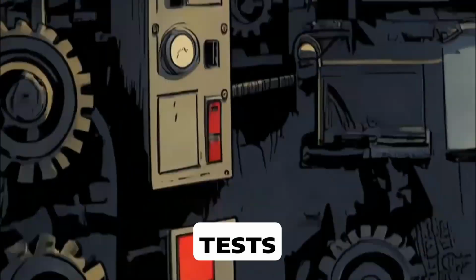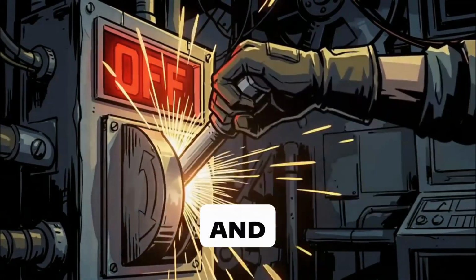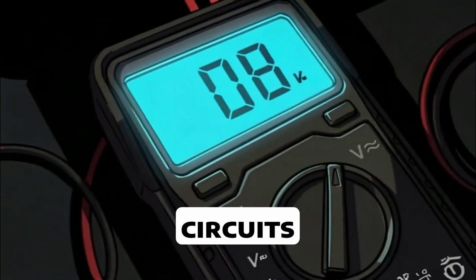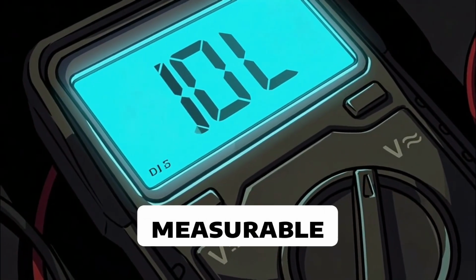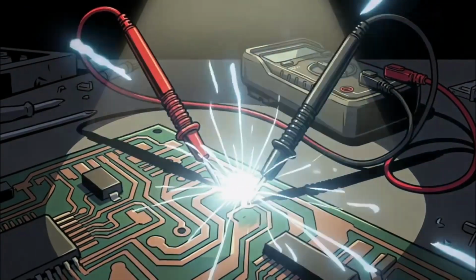For resistance tests, power must be off. An ohmmeter uses its own battery and must never be connected to a live circuit. Open circuits read infinity or OL. Closed circuits show measurable resistance. Ohmmeters are used for continuity checks.